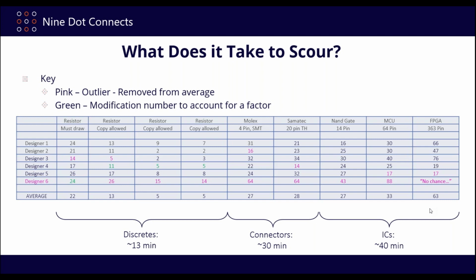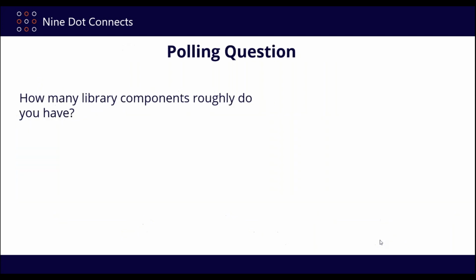You're immediately going to go to possibly a 10 or 12 layer board, maybe 8, but definitely more than possibly 6, depending on how big that FPGA is. And you probably have an employee who's dedicated to writing the code for that. So they're not a minor undertaking by any stretch of the imagination. I'd be surprised if there was even more than a dozen, unless you're in a really, really large company. Even then, usually you pick 1 or 2 and stick with those, because you know the animal you're dealing with. So I think that the average we came out with is viable.